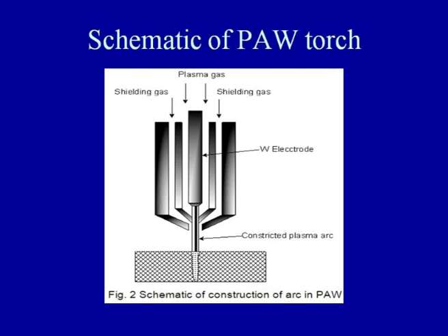from the power source between the tungsten electrode and the base material, or one additional anode can be brought in between the electrode and the base material. So, in that case the arc is struck between the plasma from this electrode and the nozzle and the anode. So, once the arc is developed, the plasma forming gas is allowed to flow through the arc zone. When the plasma forming gas flows through this area, this is the plasma annular space through which the plasma forming gas is fed in.